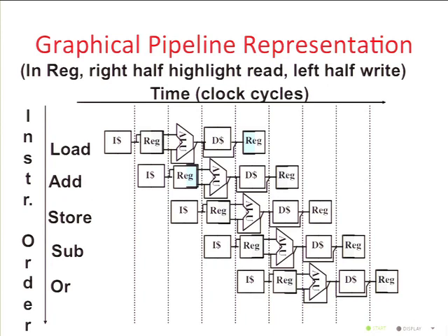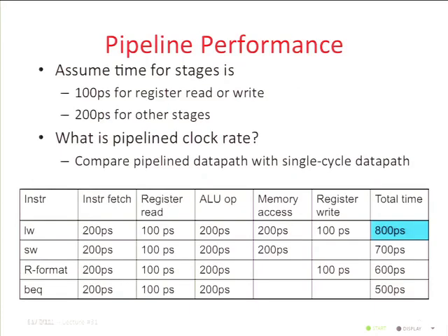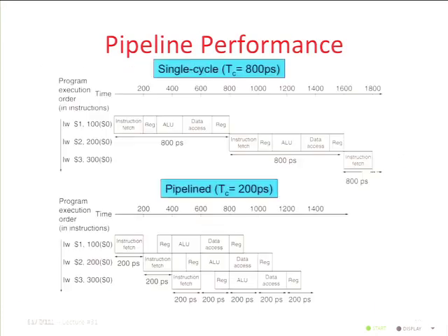So when you get into trouble with memory access, it isn't in the normal case when you get a hit in the L1 cache. It's in the other case, when you get a miss in the L1 cache, and that's another type of hazard that we'll talk about. You have to figure out how you're going to wait for that one. But in the normal case, when you're getting hits in the cache, there's no delay. You can keep going. So that's an important thing to keep in mind.